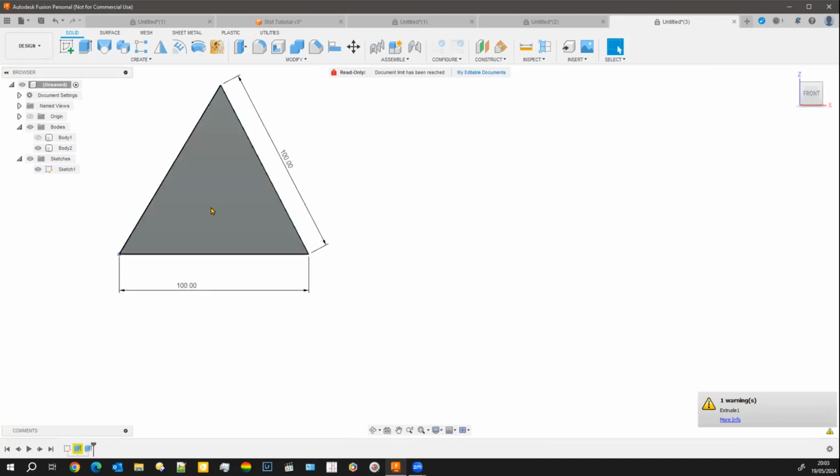If it's about the center line and the line or the shape has been drawn to a center point and you extend those dimensions or reduce those dimensions in solid mode, it will go either side. If it's not done, if it's been free drawn like this, the line will be extended from its origin.